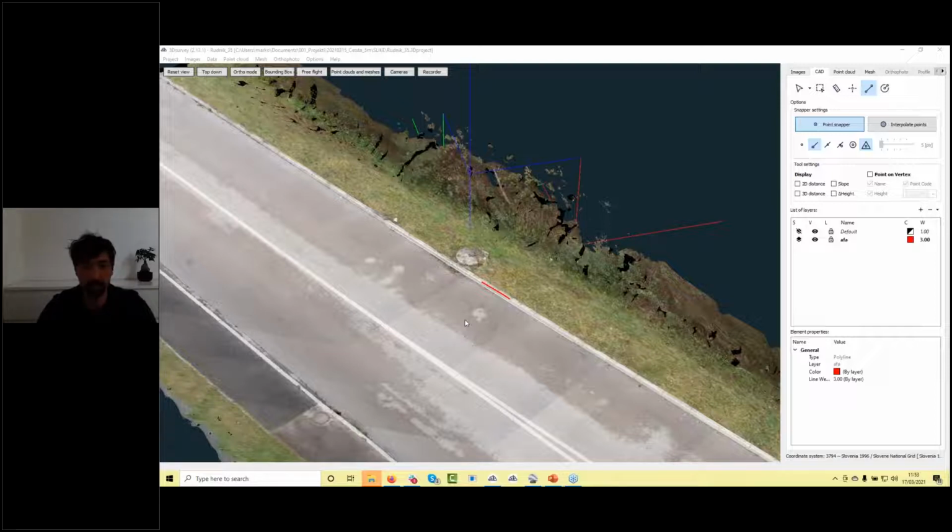So the Phantom 3 Pro has a different camera, so it's not so powerful. It's a rolling shutter camera. Of course, it also works, so you could get similar results, but definitely place more ground control points on your area. At least 10 GCP points per kilometer,